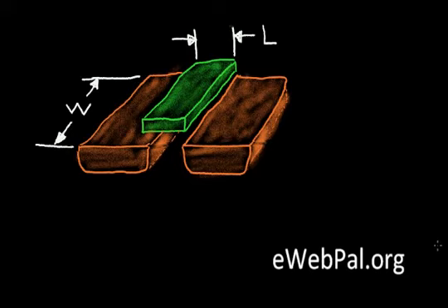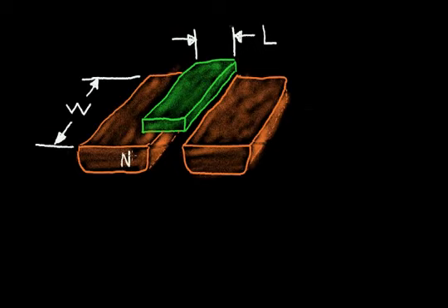In this video I want to talk about the CMOS inverter timing and layout. By timing, I mean how fast the inverter can respond. If I give the inverter an input, how fast can the output of that inverter discharge a capacitance? Now let's start by reviewing the MOSFET transistor. Here I have an N-channel MOSFET where the orange is an N-type silicon.